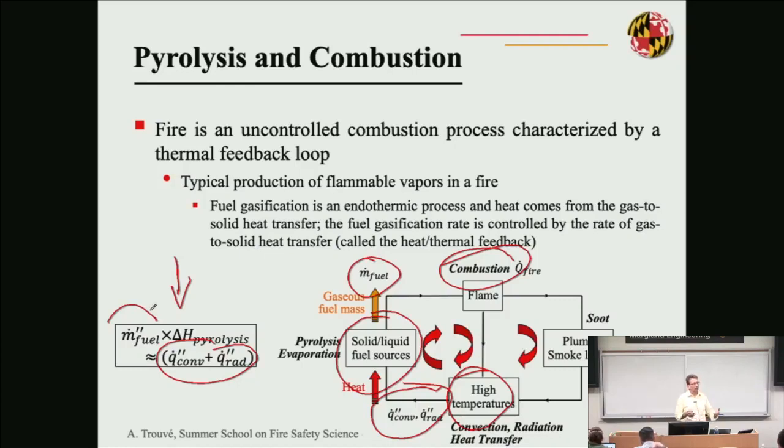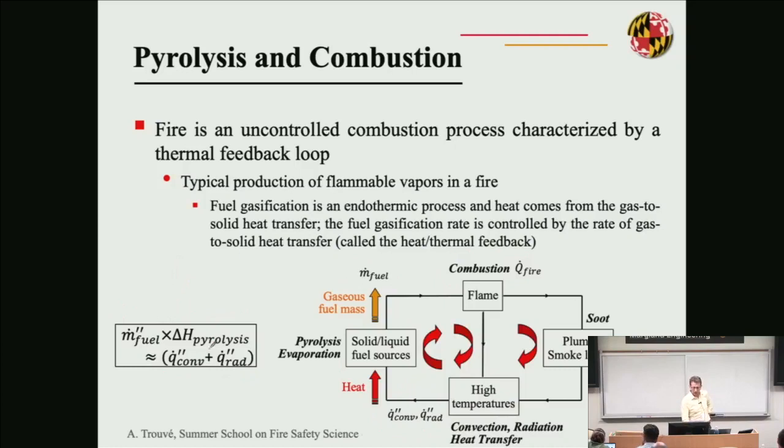So the mass rate of evaporation of water in my example, times the heat of evaporation of water, that is going to be the way the liquid water is going to use the incoming heat to evaporate the water. So this is a very simple heat balance statement that is only an approximation in the case of pyrolysis processes, but is good enough to show the strong coupling that we have between the heat transfer measured by the heat flux and the release of flammable vapors, the release of fuel from the combustion process. So everything is heat driven. So the pyrolysis is heat driven.